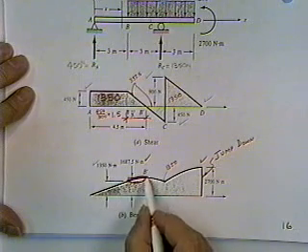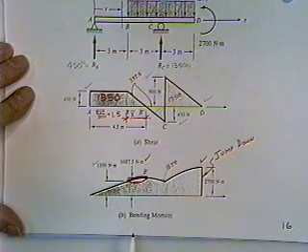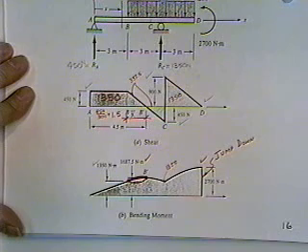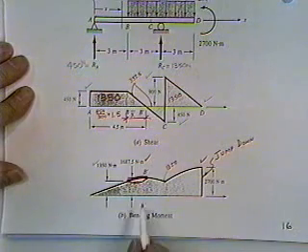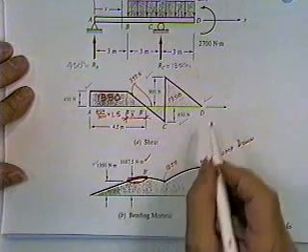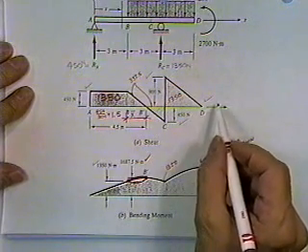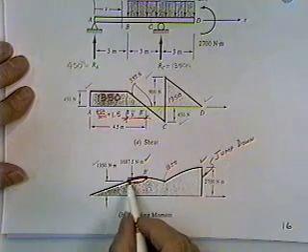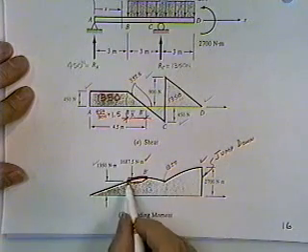Now, if you're just looking for the peaks, it probably doesn't matter. You don't have to spend a lot of time worrying about which way it goes. Not only that, this moment diagram is the end of things. We're not going to the next diagram. If we were going to the next diagram, I'd be very interested in which way that curve goes, because the area would be different. Every now and then you'll find that kind of a curve comes up on your shear diagram, so you really should know how to tell whether it's the high part of the curve or the lower curve.